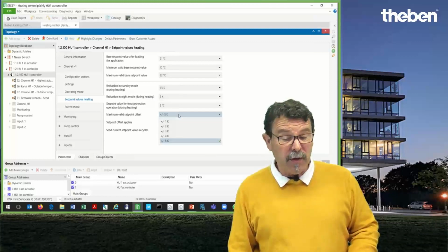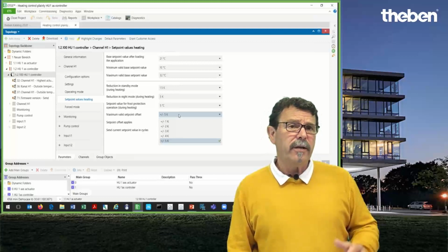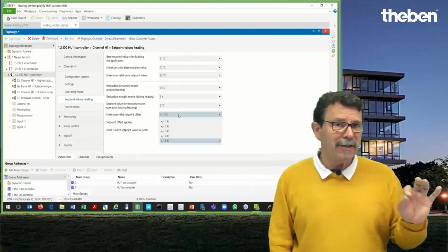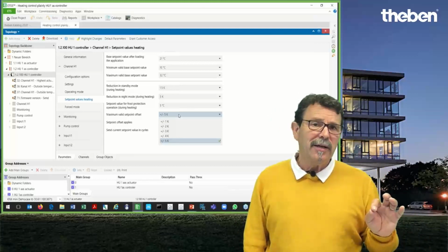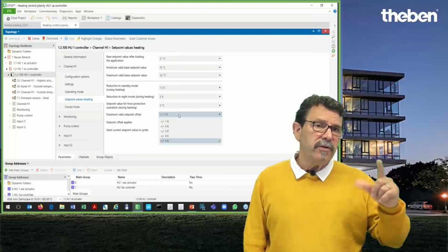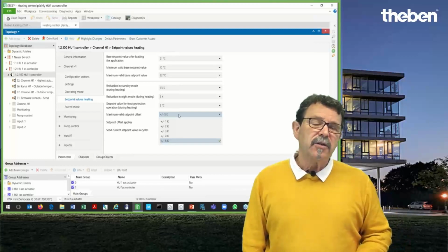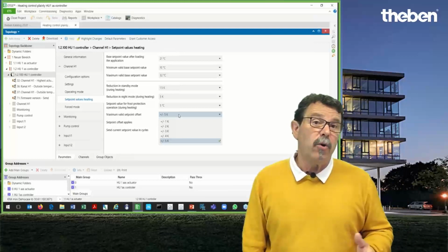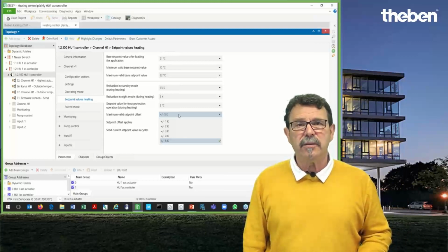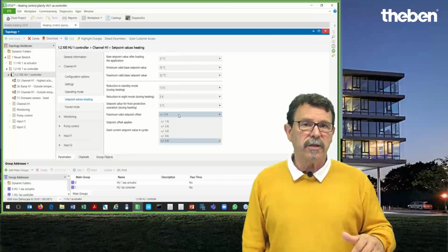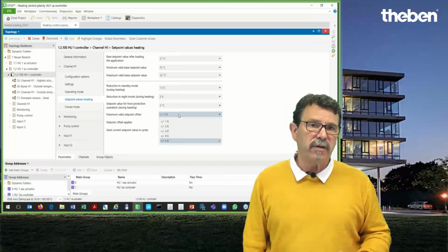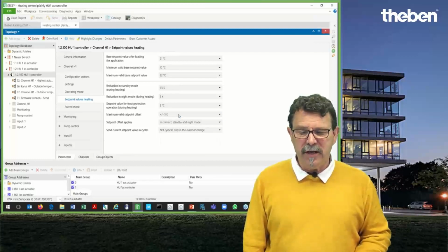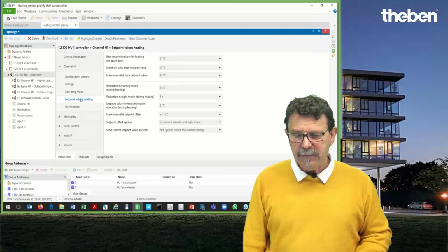This one could probably be of interest when you intend to integrate this kind of small, smart and fancy heating control into a visualization. So here you can adjust the limit finally. So how far can the set temperature be modified? Just 1K up, 1K down, or up to 5Ks up, 5Ks down. That's up to you. This you can limit in these application settings.